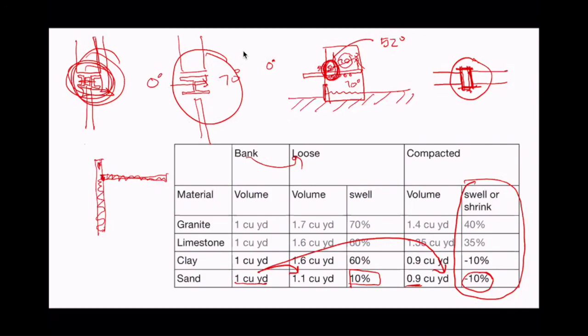Inside is 70 degrees and humid, and the steel is very cold. Especially if air gets in through here, there could be significant condensation, especially in a cold climate, on the parapet. So there is a moisture component to thermal bridging for sure.